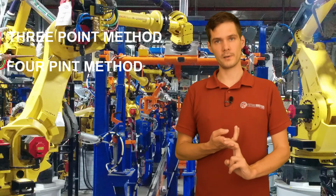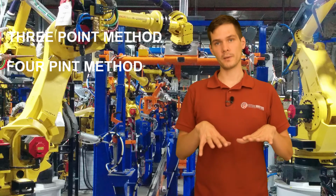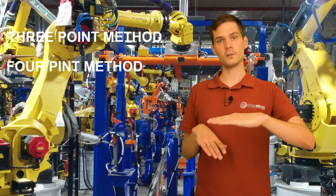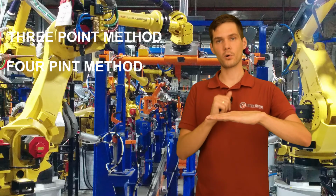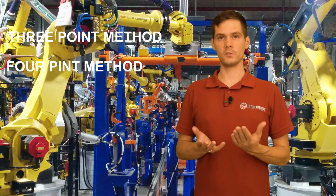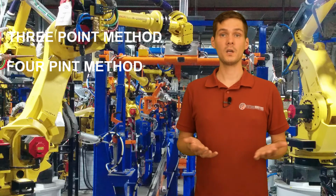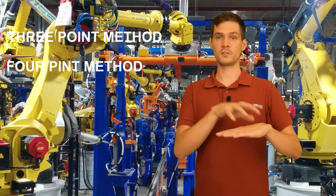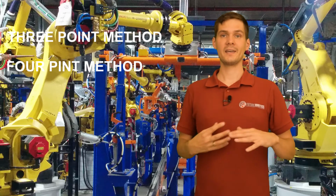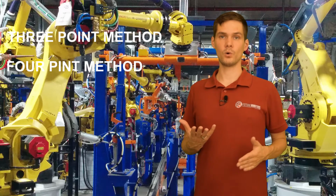There is a 4-point method. And why do you have the 4-point method? It's an extension of the 3-point method. So you're going to make your frame, and with the 4th point you are moving it to some point. So when is it useful? Imagine you have a pretty big table, for example, or a table with a lot of fixtures on it, with a lot of obstacles that won't allow you to actually teach the frame as you want.